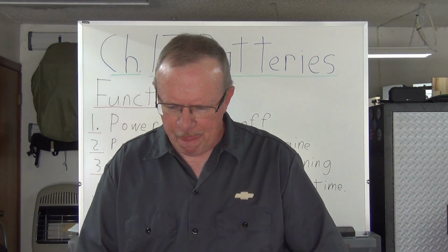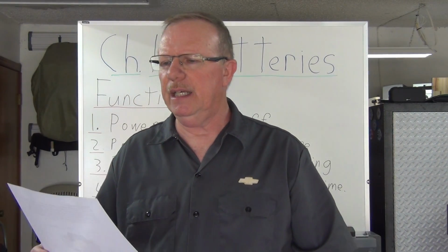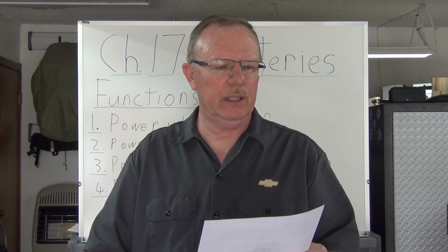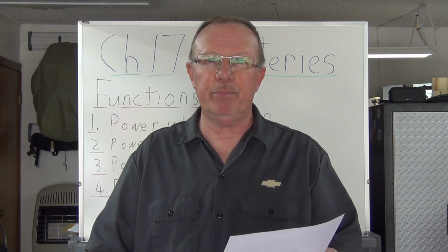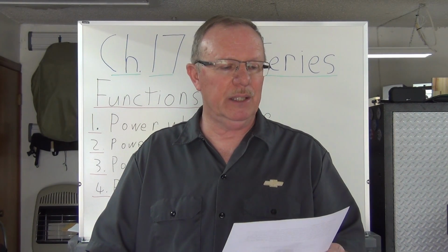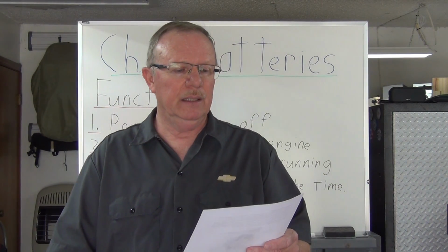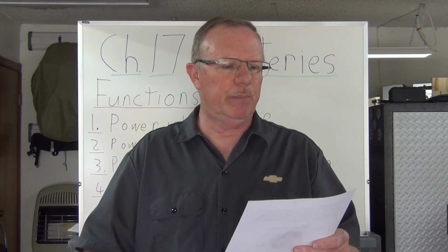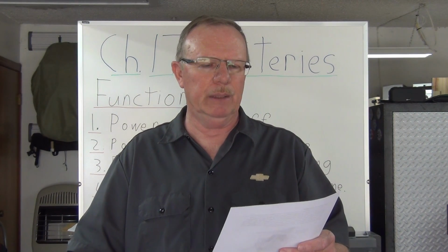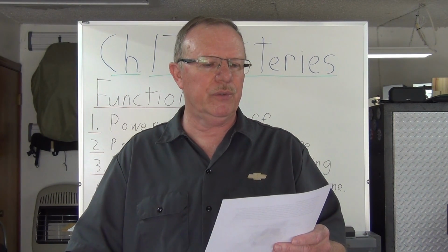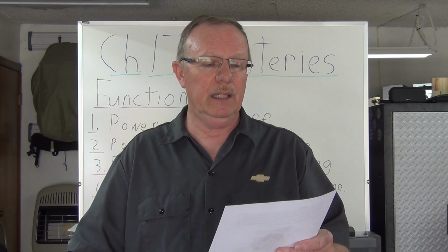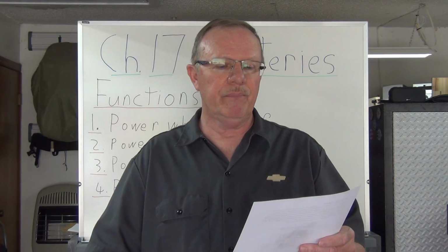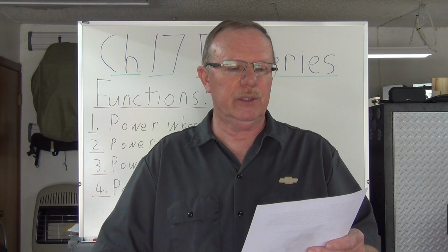All right, page 7, battery cell element. It says the key to battery operation then is the cell element. The positive plates and negative plates are connected together by separate plate straps. These groups of positive and negative plates are then placed alternately, okay, separated by micro-porous separators. Assembled together, the plates and separators form a battery cell element. Grouping of the plates in this way serves to enlarge the surface area between the active materials and the electrolyte, thus allowing a greater amount of electricity to be created. In other words, the battery capacity is increased because of increased surface area.